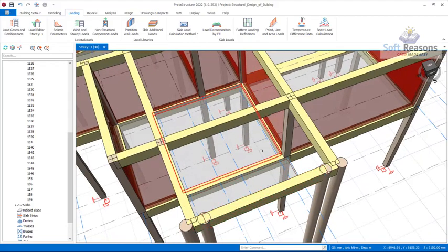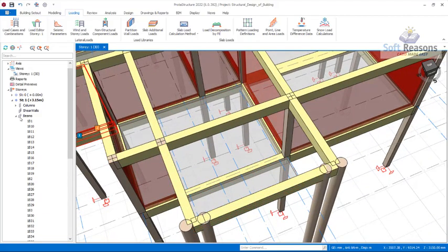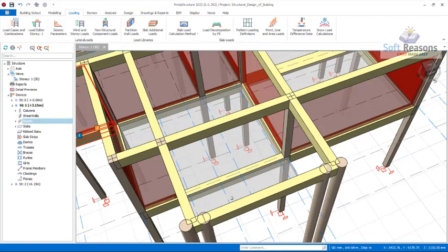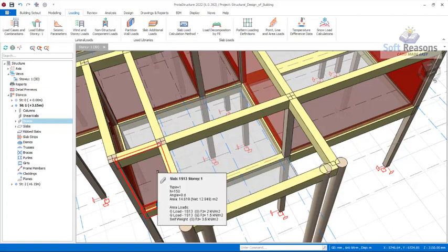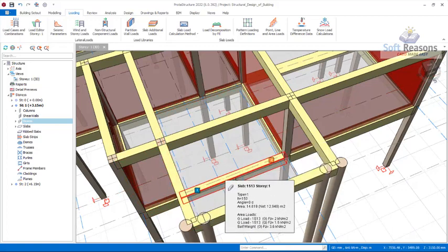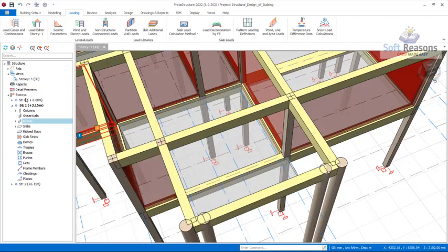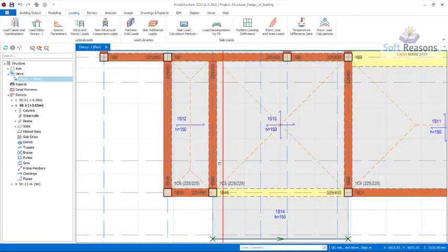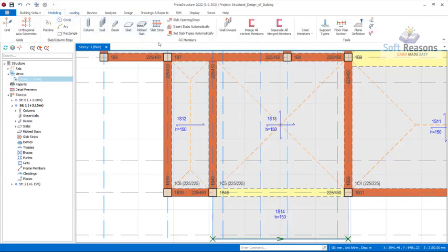Okay, so let's navigate and then apply that wall load right there successfully. Now the wall load goes along the slab. Okay, it goes along the slab because there is no beam to actually carry it. So for that reason, we are going to be considering a line load. All right, so we consider a line load here. Okay, so to do that, what you have to do is to get to the modeling, and then you will find slab.